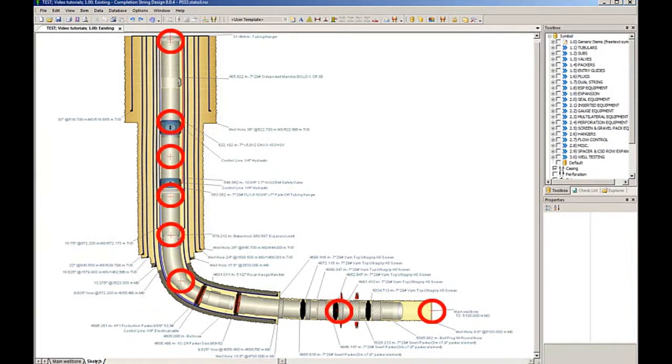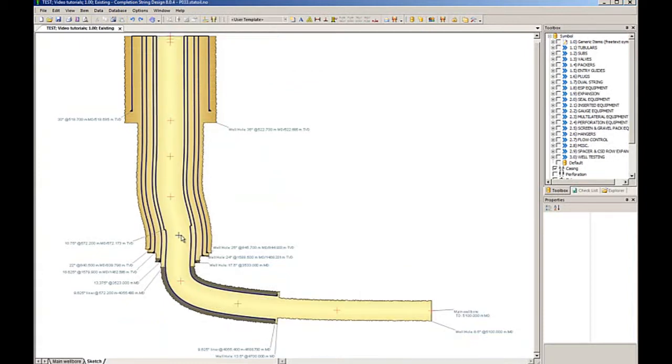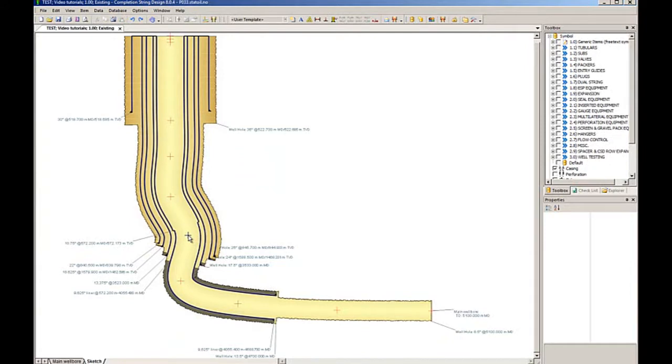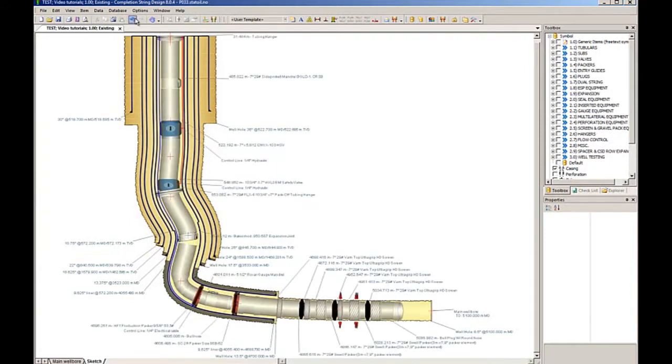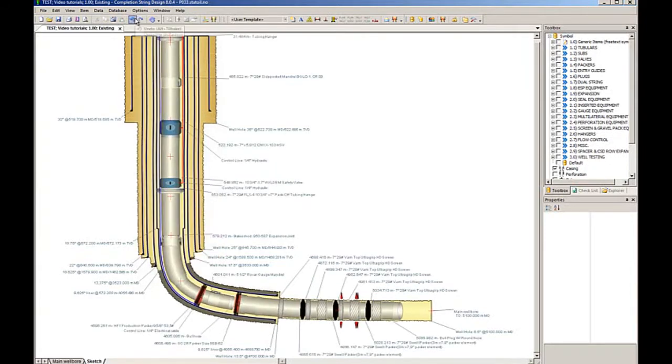You can change the curve by using the red crosses called control points. Drag them around until you get the desired shape. By moving the mouse pointer over a control point, the red control point will be highlighted to show that it can be moved. Click on the cross and move it to the position you want. Then release the mouse button. In this operation, the casings will be shown so that you have an impression of how the result will look.